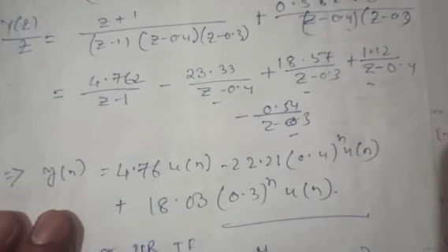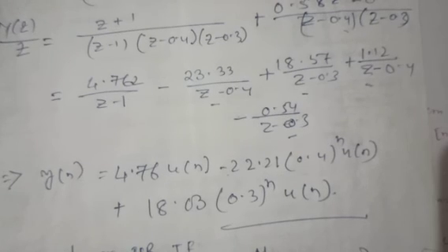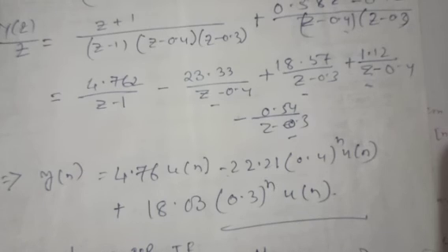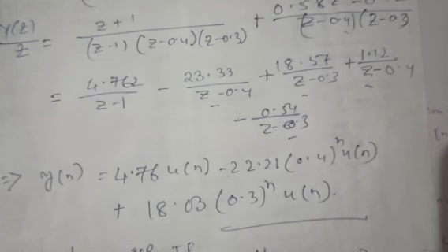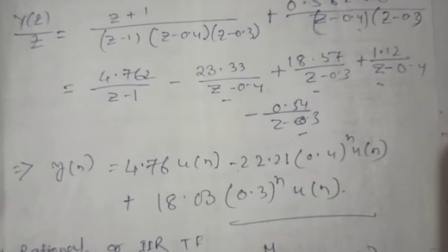So the same solution, if we would like to do using the process of solving the difference equation, then we have to go for the method that I explained, the forced response method. Okay, to find that, because it's a forced response. Forced response means the zero state response. Okay, output due to the input only, and finally the total solution is the natural response plus the forced response. Okay, so the process is lengthy, but while you use the Z transform, the process becomes simpler.